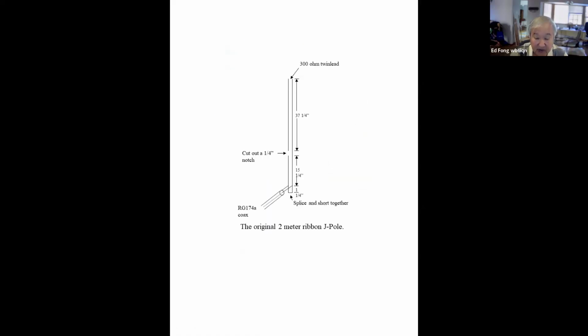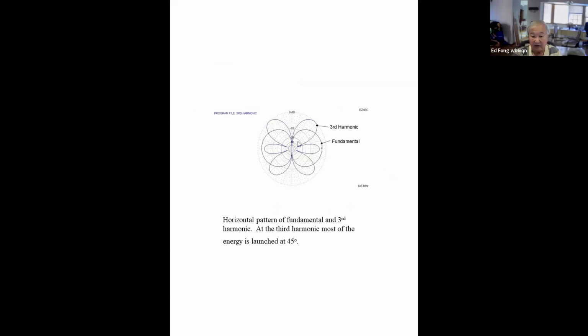So at UHF, when you shove the signal through, it also comes through here. I see an open circuit. That's great. If you just left it this way, at UHF, this sees a match. It's the third harmonic match. That's not the problem. But at UHF, it wants to see 12 inches, but this is like 37 inches. That's not good because it sees 12 inches. The current goes up, now what do I do? It continues. You haven't stopped it. And it continues out of phase. That's the key. That's why you get this pattern at UHF.